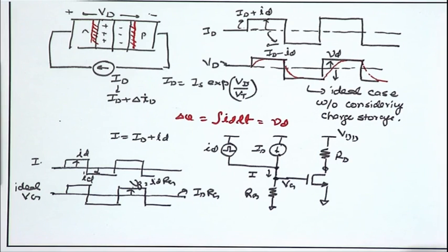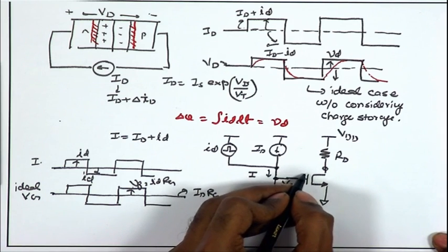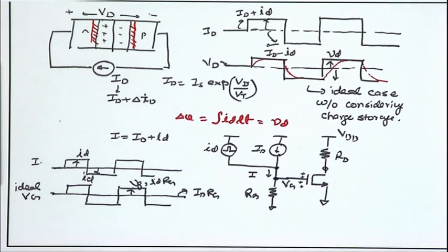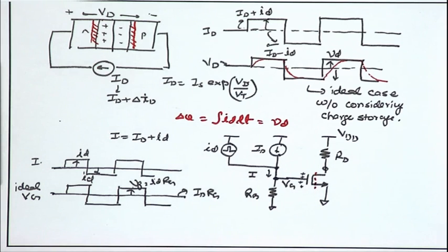But ideally, once again, what is going to happen, in order to increase the voltage over here, you are effectively changing the VGS, and whenever you change the VGS, these positive charges must be balanced by an equal amount of additional negative charges in the channel.